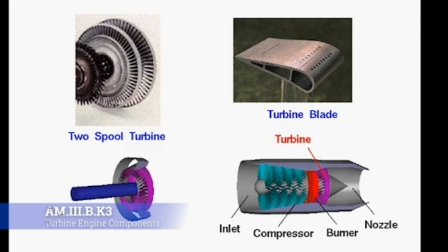However, this, just like a propeller, instead of going up because it's attached to that main shaft, is going to cause it to rotate. And as that happens across all of them, it starts to build this rotational speed higher and higher and higher. So it transforms a portion of the kinetic velocity, that kinetic energy of those exhaust gases, into mechanical energy to drive a gas generator and compressor up front. So as it starts to spin, it's actually going to help create the self-licking ice cream cone that is a